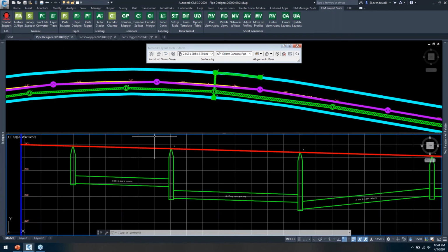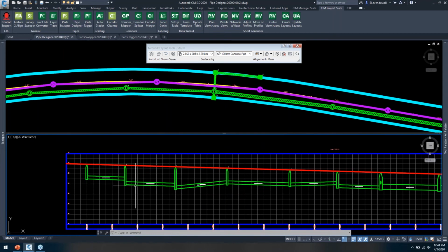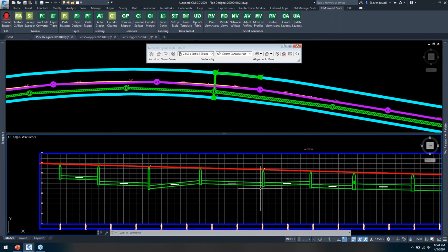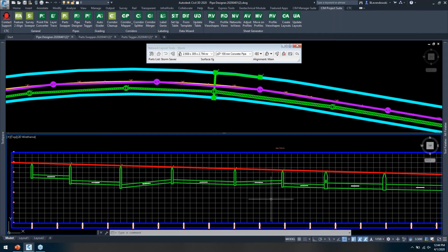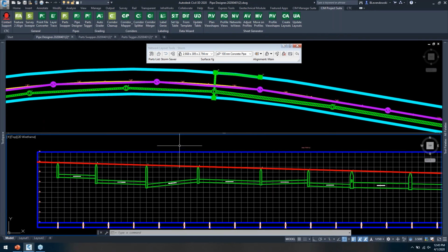And what I want to think in terms of is holding a constant slope and perhaps an invert drop across a set of pipes and structures. Start at a given invert and then go from there, right? And if I find that that run doesn't work because it's too close to a sanitary line, for example, how do I move that whole line up or down? It's a very tedious thing in Civil 3D.